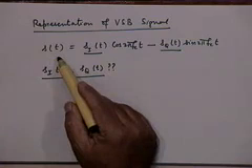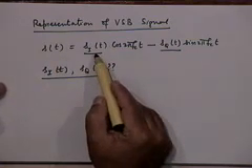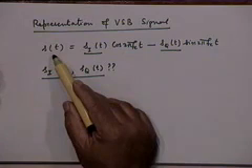Remember we discussed quadrature multiplexing and demultiplexing, right? If I want the in phase component from this signal s(t), what should I do? I have to do coherent detection with respect to cosine 2 pi fc t. I must have a coherent detector with the local carrier of cosine 2 pi fc t as the carrier signal, multiply these two and pass the product through a low pass filter.